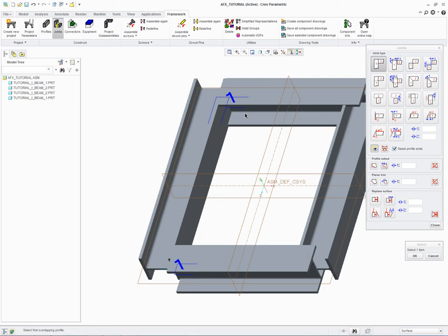The joint is not an assembly level cut. It modifies parts, so the modification to the end of the profile is in the profile part. There are also symbols now, a full symbol on the part I first selected, and a half symbol for the affected areas. I'll fill in the rest of the joints until all the pieces line up. If I misplace a joint, I can use the Delete Joint tool.